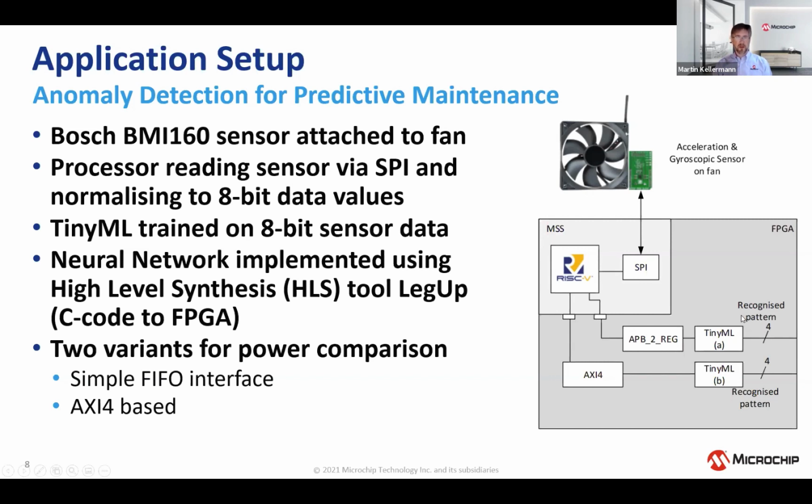In the C code that Altaf was showing, there's also a little test bench that is very simple and easy to digest, but it needs to be changed a little bit to be usable here on the FPGA. What I wanted was not just a data pattern showing me which is the highest likelihood, but really 4 signals showing me this is the normal one, this is the obstruction, or whatever it is. That's why I added a little bit of C code that does a comparison on the data and ends up with 4 bits showing what is going on.